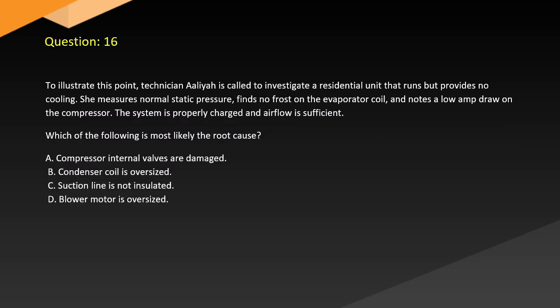Question 16. To illustrate this point, technician Alert is called to investigate a residential unit that runs but provides no cooling. She measures normal static pressure, finds no frost on the evaporator coil, and notes a low amp draw on the compressor. The system is properly charged and airflow is sufficient. Which of the following is most likely the root cause? A. Compressor internal valves are damaged. B. Condenser coil is oversized. C. Suction line is not insulated. D. Blower motor is oversized.